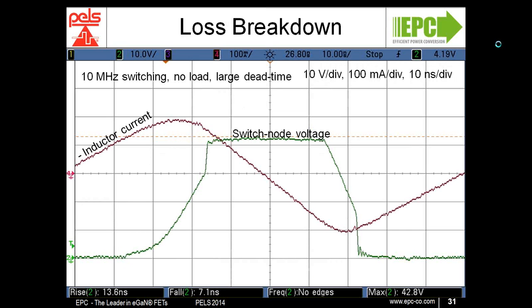So what we can say from this is that on the falling edge, there is no diode reverse recovery. So the falling edge is purely COSS dependent. From this, we know how much the devices are, and we can calculate how much the IC contributes to that. If we assume it is symmetrical, the same COSS will impact the rising edge as well. Any additional time that is taken on the rising edge is attributed to the diode reverse recovery.